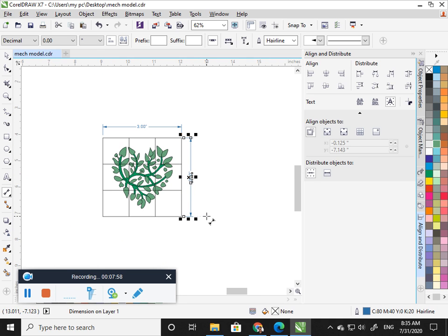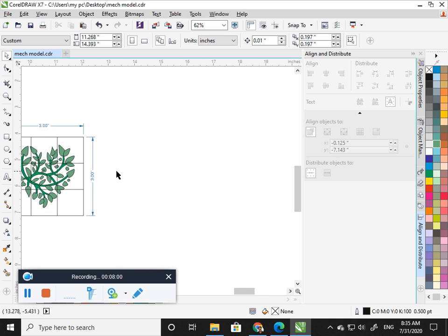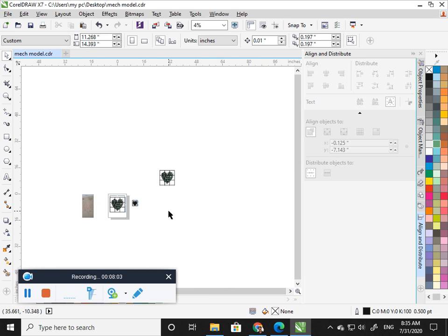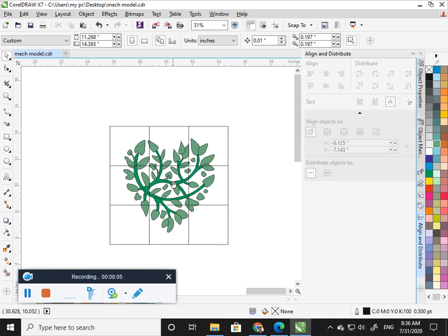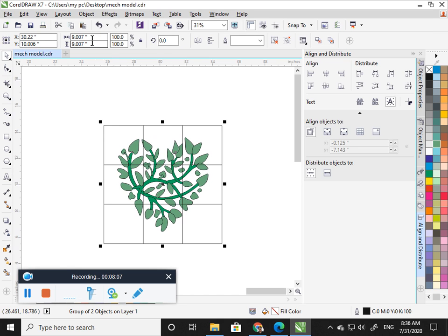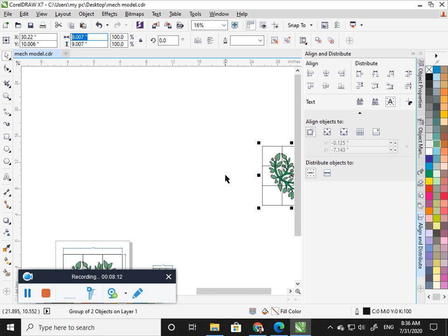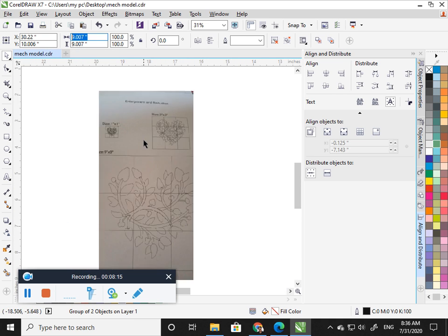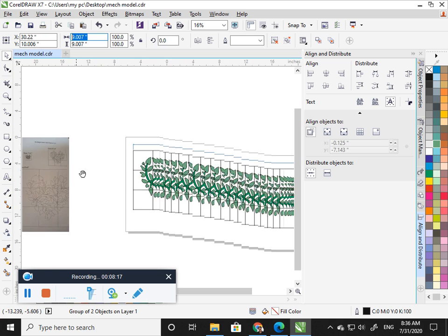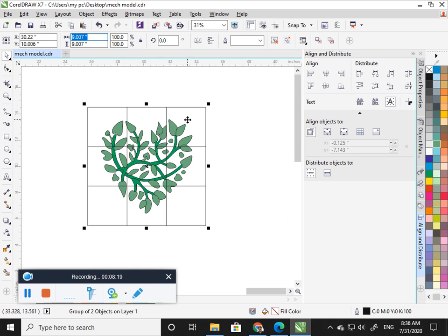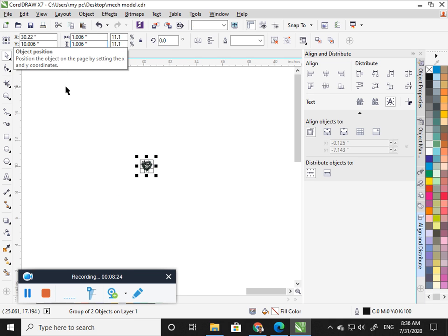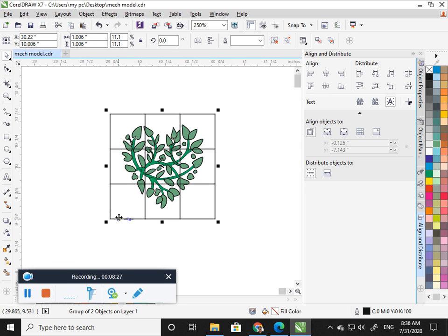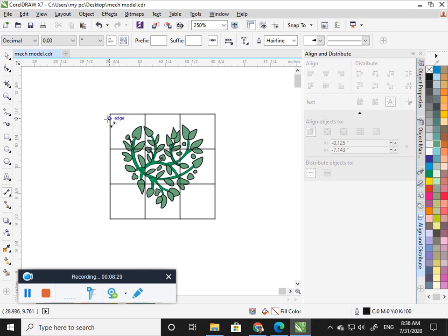Okay, and now I need to compress one more box into 1 by 1. So where is it? Yeah, this one. So select it and change this to 1 by 1. That's 1 by 1. Okay, so it's small. So select this and change the value to 1 by 1. It's very small. And now you can give the dimensions also, parallel dimensions, by holding endpoint to endpoint.